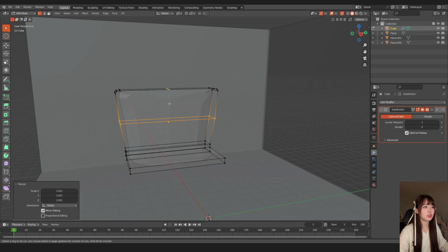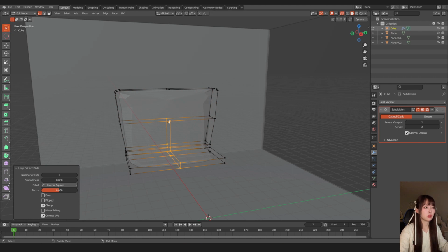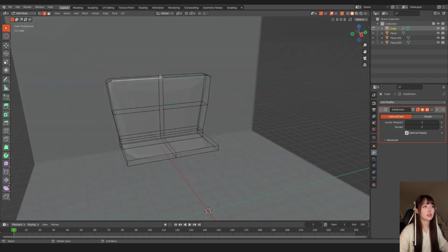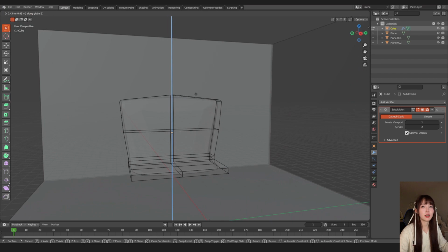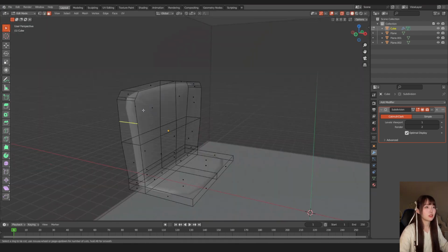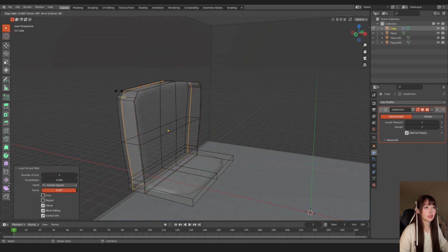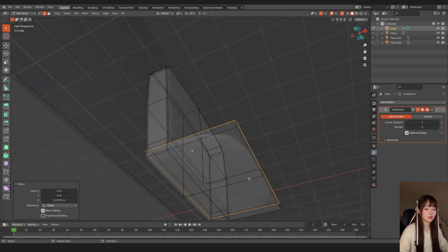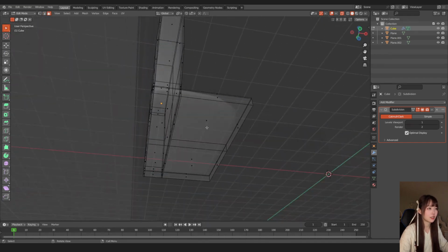Because I have this edge loop, I'm no longer able to do a loop here, but no worries, we can join these two vertices: select two vertices and hit J. I select this edge, G and move up a little bit, G and move up, Control R and Control R to make the back sharp, and the bottom, which we can't see, we can delete it.